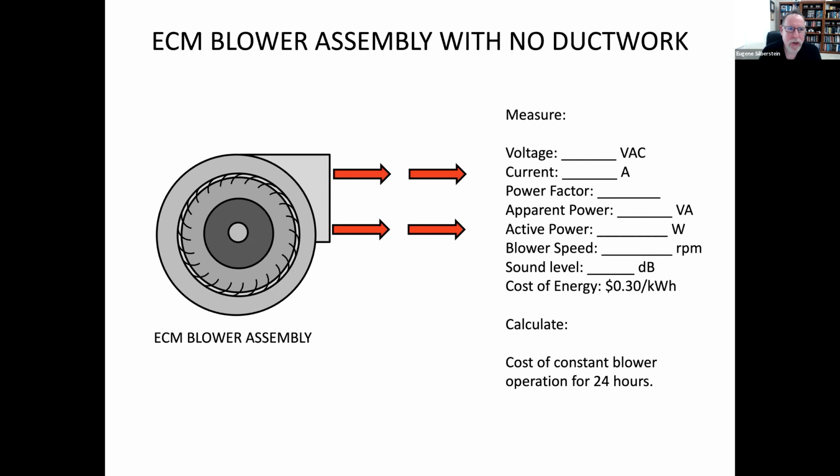So I just want to share with you a couple of things that I have my students do. So I take that ECM blower assembly with no ductwork, just the blower, and I have them obtain information, the voltage, current, the power factor, apparent power, all of these parameters, and also measure the sound level.